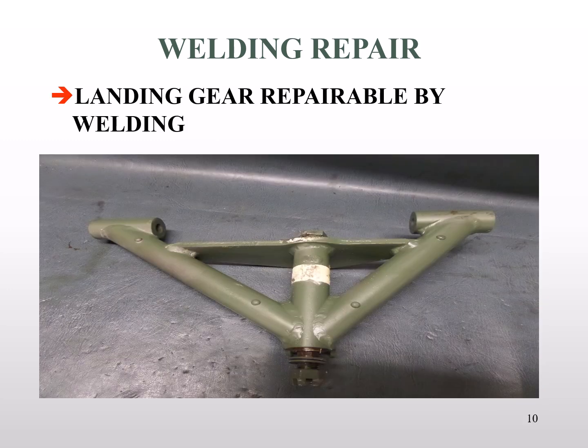Parts are repairable by welding if they did not go through some form of a heat treatment, and that's going to be true for all welded parts. If they were welded and bolted on, then they're generally repairable by welding. However, if they were welded, then put through some form of heat treatment, we cannot repair them in the field because we typically do not have access to the heat treating equipment to reestablish the hardness of that part.